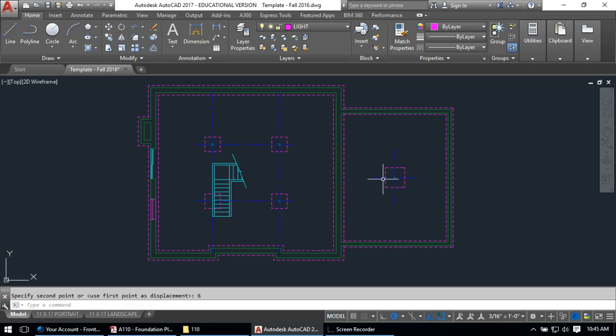All right, we are getting near the point where most things are drawn. We still have to draw the insulation, which is that really skinny line around the exterior of most of this foundation. Again, there's no dimension there, but if we look at our notes on page 3 of the instructions, we are adding 2-inch insulation, so we can assume that is indeed 2 inches.